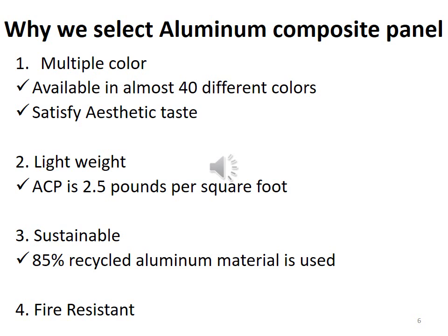The last property, which is very important, is fire resistance. As sandwich panels have different fire behavior, resistance and reaction depending upon the foam which is used for aluminum composite panels, it depends upon which kind of core you are using to fabricate the aluminum composite panel.